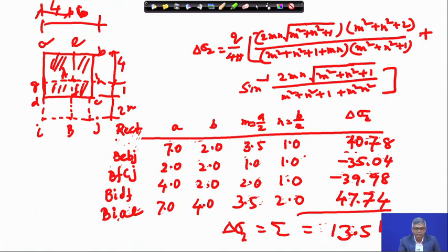So, you can see that this is the loaded area. Inside the loaded area obviously pressure will be more, and when we go away from the loaded area, it will be less. Obviously, we got 137 previously, and when I have gone out of this, it is only 13.5. So, this is another application of how to use the corner formula in different ways, shown in this same problem considering point A and point B.